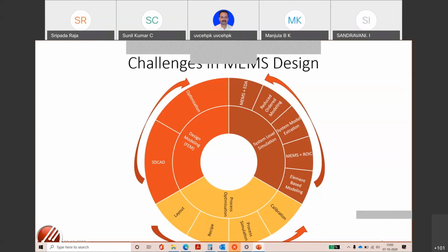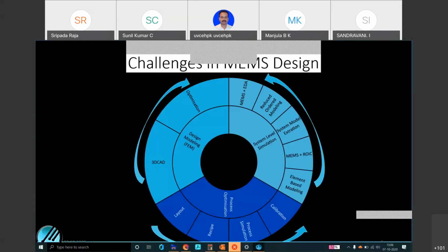The only difference between the two is the MEMS device is in the scale of 1 micrometer, okay, or in the micrometer scale, whereas the circuit is in the nanometer scale. So both cannot be fabricated together. So what they do, they separately fabricate both of them and then place next to each other and then connect them like a wire bond, and then they encapsulate with standard packaging, IC packaging methods.